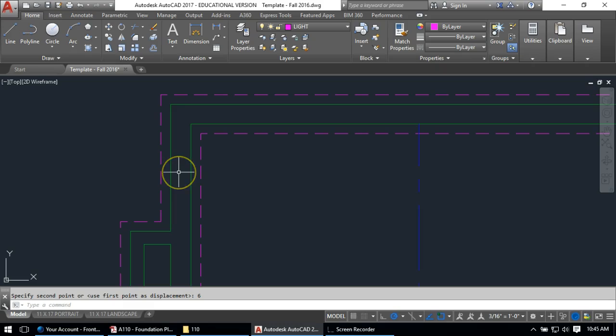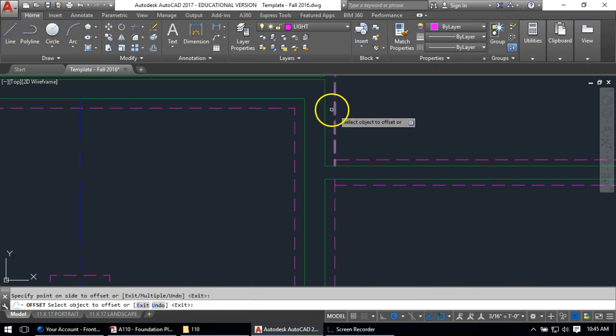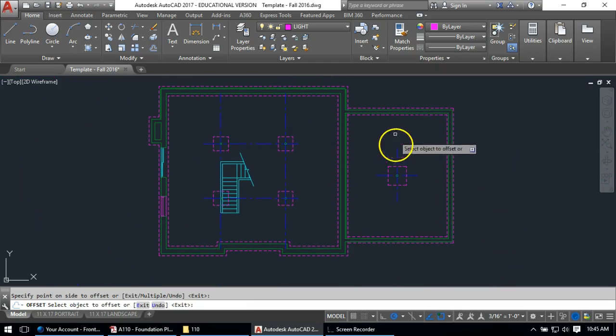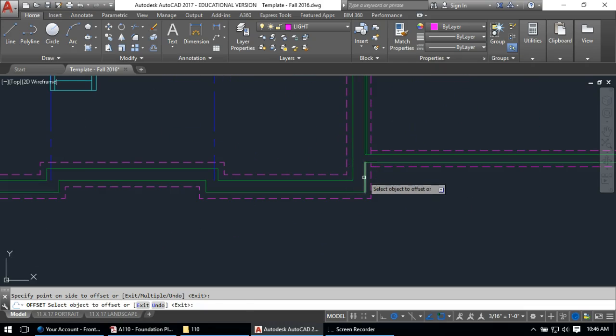So I'm going to go up to my foundation wall wherever it exists and offset 2 inches. So that's around the top, around the side, inside here. Now this, again, I don't see in the plans. This might be some garage or shed or something, so we're not putting insulation around it. We wouldn't need it in that case.